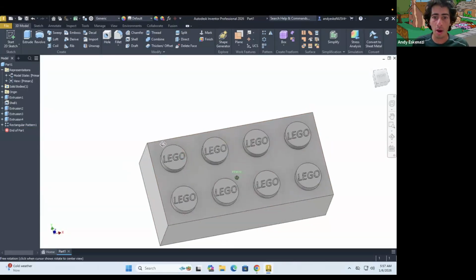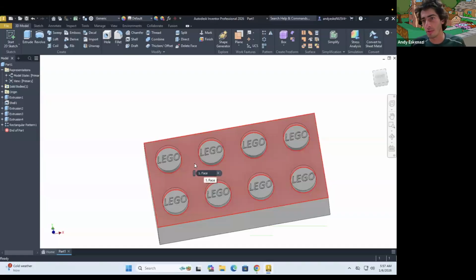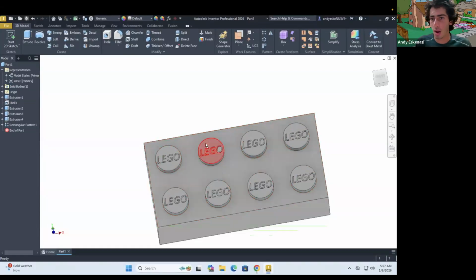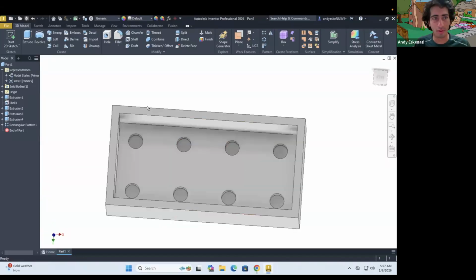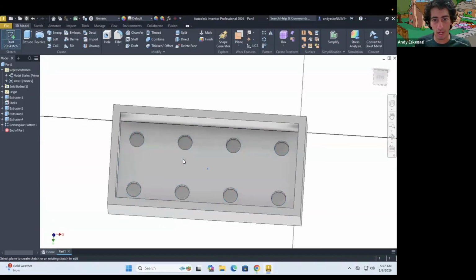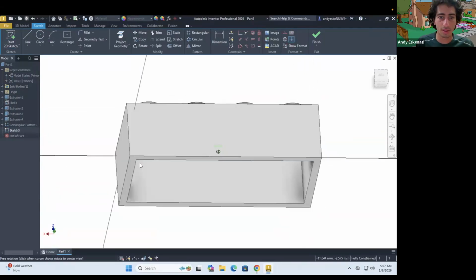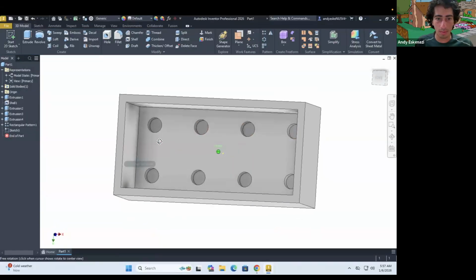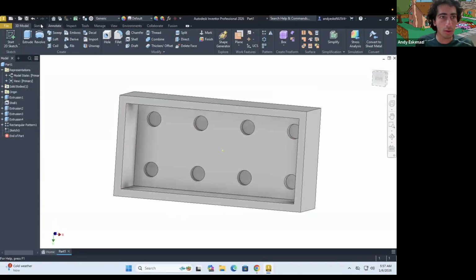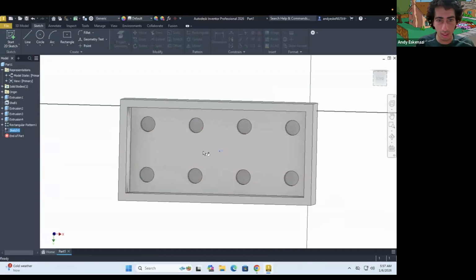So that's good. Yes, if we had wanted to add the fillets, we would have done them before we had done the patterning. That way, the fillets would have patterned as well. But for now, we're gonna leave this like this because I don't want to explode the model with a lot of details. And I'm gonna go now over here, and we know that that's our base. Oh, that's our base brick. So what I'm gonna do is go here to sketch. I think I was in here. So let's do edit sketch right there.